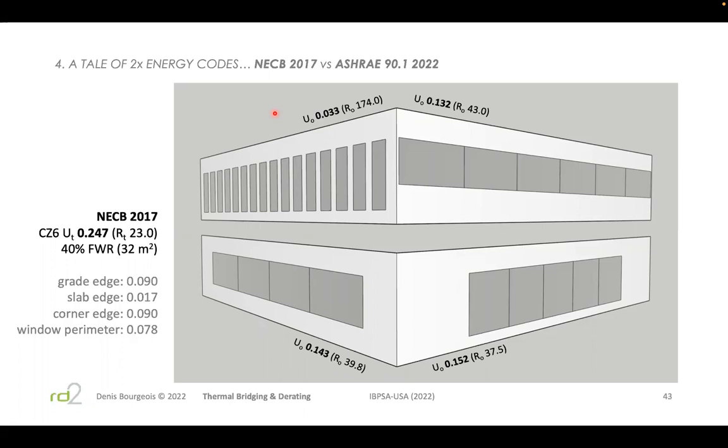this is what you would describe in your building specs, or this is how you would describe it to a contractor. You need to come up with an R37, an R30, close to, in 3 cases, more or less R40 in 3 cases. But the case with the very numerous individual, what we say in French, meurtrières, very narrow windows, you're looking at an R174.